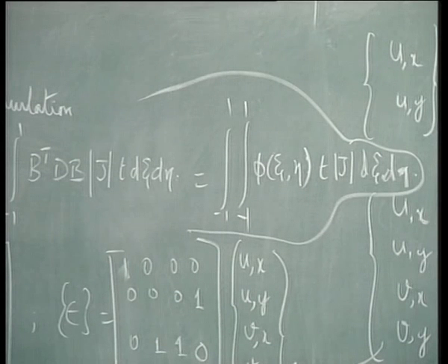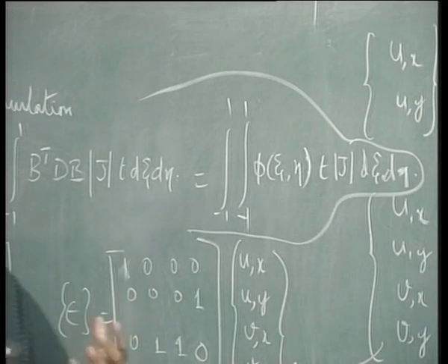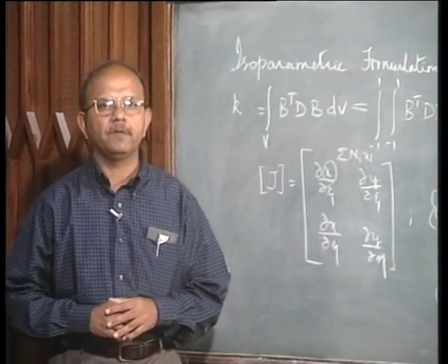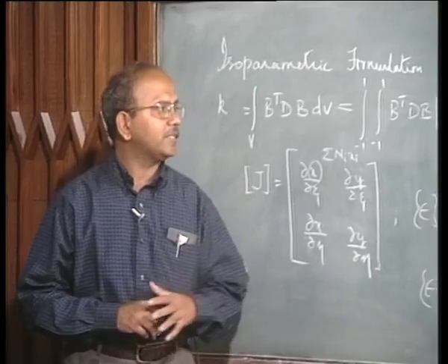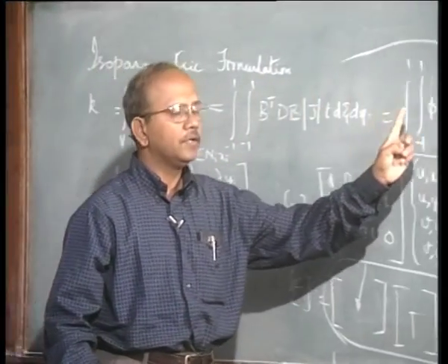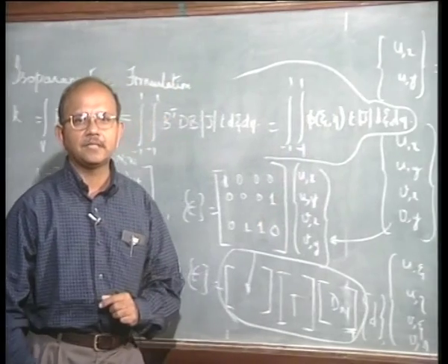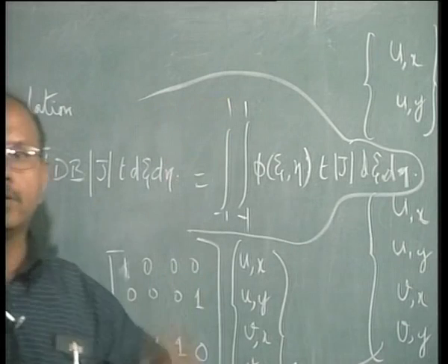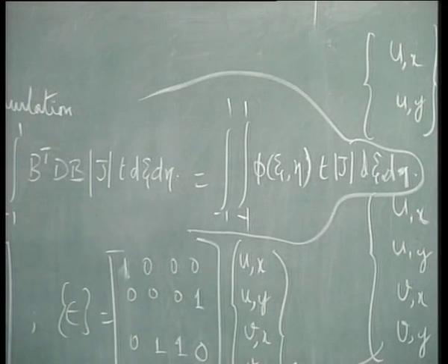Okay. Now this is a very happy situation, because the integral was a surface integral and volume integral, which was a bit difficult for you to derive, especially when the shape is quite bad. Now what is that we have done? We have replaced that by means of a psi eta coordinate system, and the coordinate now varies only from -1 to +1.